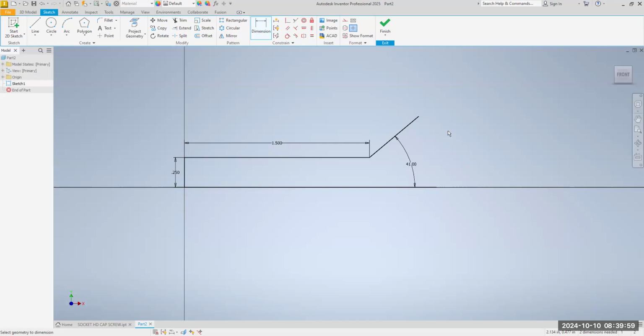We're going to take 6.375 divided by 25.4, and it's basically 1/4 of an inch. I don't know why they didn't just leave all the dimensions in English units, but they didn't. So that dimension K, the thickness of the head, should be 1/4.